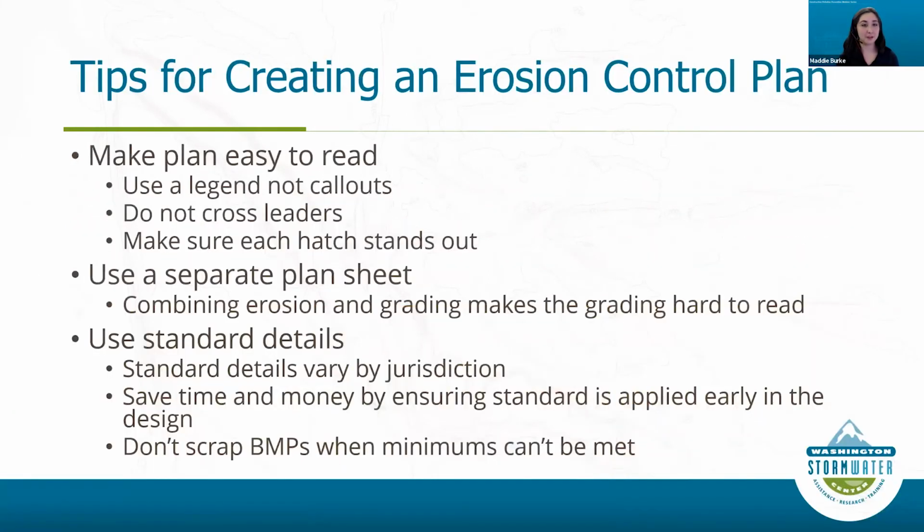So when you are creating an erosion control plan, here are some tips to keep in mind. You want to make your plan easy to read. You want to use a legend and not a lot of callouts. You don't want to cross your leaders, and you want to make sure each hatch stands out. If it looks confusing to you, it's definitely going to look confusing to your contractor.